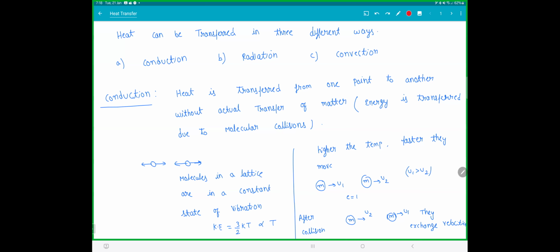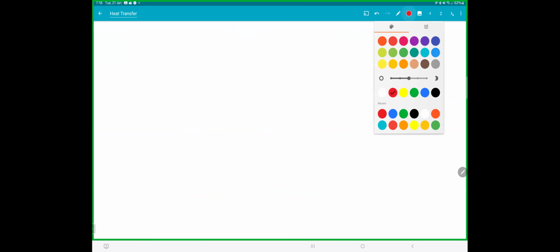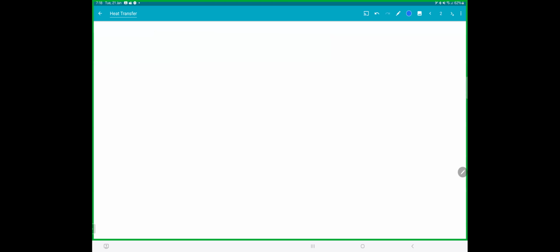Same way, when you're walking on your terrace during hot summer without sandals, your legs burn. But if you wear sandals, your legs don't burn. Even though the temperature is still the same, the heat transfer is less. Clear? So what we humans experience is not temperature, we experience heat transfer, the flow of heat, how fast it flows. If the heat flows faster, we think it is more cold. That is the reason metal feels more cold than wood at lower temperature.